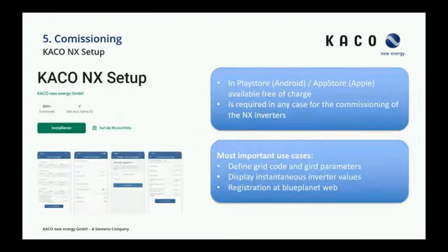Now we can start with the commissioning part. How I said before, this is only possible with the app KACO NX Setup. You can find this on the Play Store if you are using an Android smartphone, and on the App Store if you're using an Apple smartphone. This app is for free. Yes, it's required in any case for the commissioning of the NX inverters.